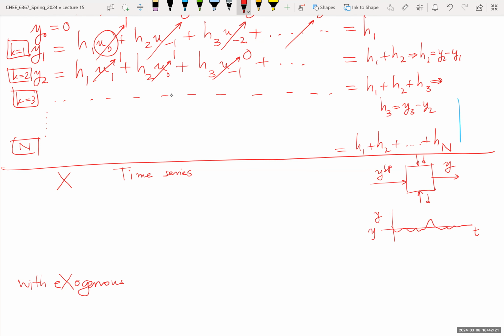So this is the value of the set point, or in deviation form, this is the 0 value. And my closed loop behaves like that. Why isn't the output exactly at 0? Because there are disturbances. Okay? There are random disturbances. Disturbances may be up, down, steps, white noise, Gaussian noise, all of the above. Who knows? Okay? The control system, so this is a closed loop system here. The control system keeps the output at its set point.